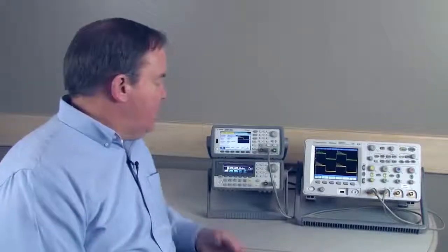The two waveform generators we have here represent two different generations. The older one on the bottom is a direct digital synthesis waveform generator, called DDS for short. The top is the Trueform generator. The Trueform generator plays every single point of your arb every time it plays the cycle. We're going to show you how a DDS generator that is unable to do this can sometimes cause your waveform to be an unexpected shape.